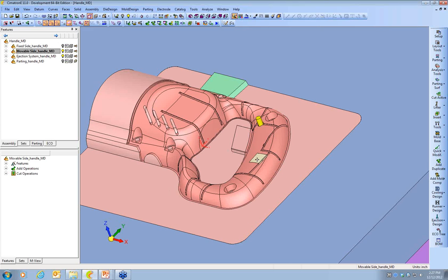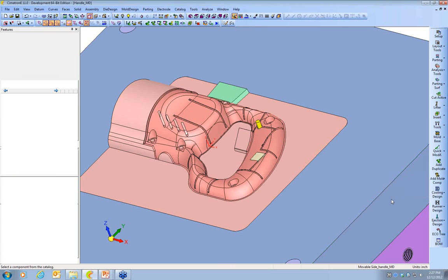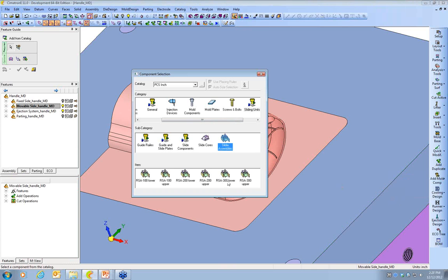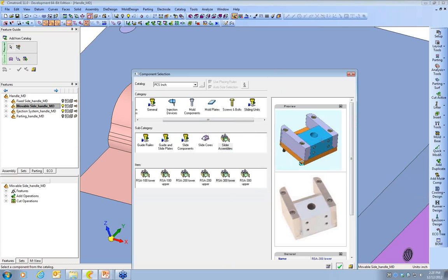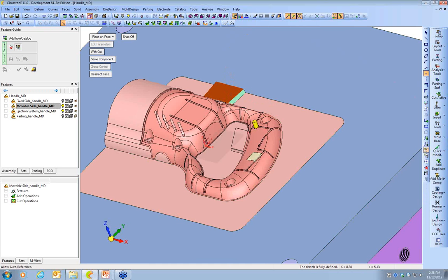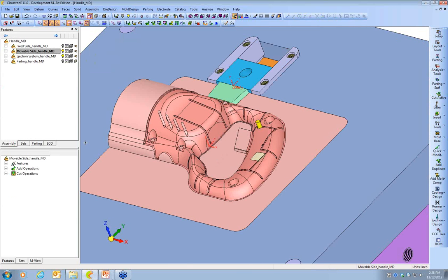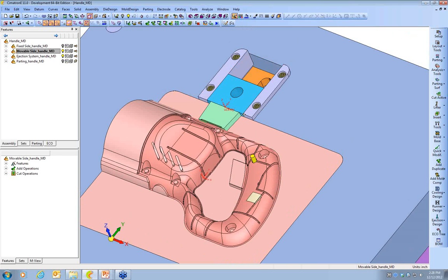And, strong catalog and cutting tools are really one of the reasons Cimatron has always excelled for tool design. Something like a small assembly that we need for our slide, I can go out and look in the catalog, and I can grab just what I need. It's easy to select. It's easy to position stuff in the tool based on faces and points that we're working from. And we've got a parameter here with cut. So that's going to create all the pockets and the screw holes. They come right from the cavities. And of course they follow along as the parts may move later on too.